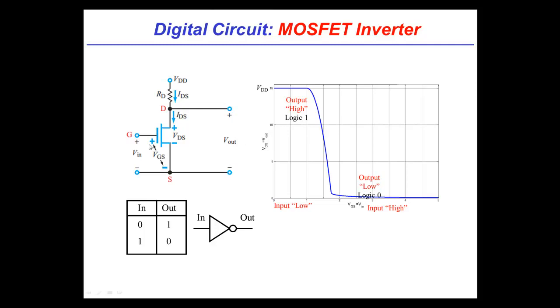So now take a look at something very cool as a consequence of how this works. If I put in a very, very low input voltage, let's say I put in 0, so identically 0, what state is the transistor in, Vic? Okay, well, I told you earlier that when there's a low gate voltage on that transistor, it's going to be off. So that transistor will be off. In other words, no current will flow through it. Right, no current's flowing through. So this IDS is 0. This is doing nothing. It's as though there were an open between D and S.